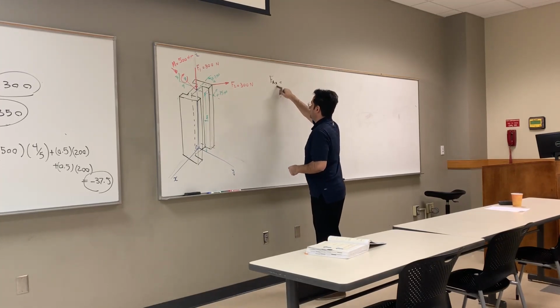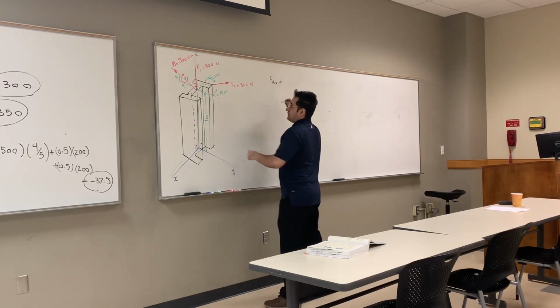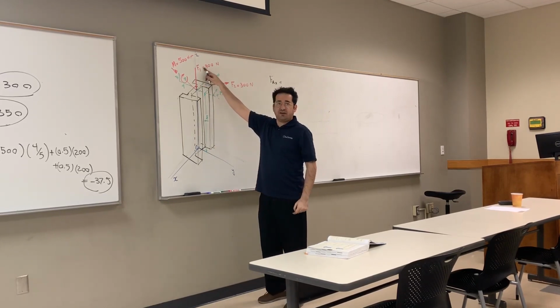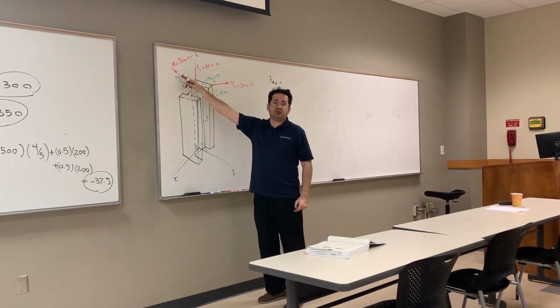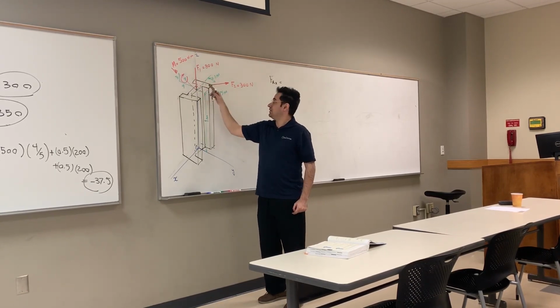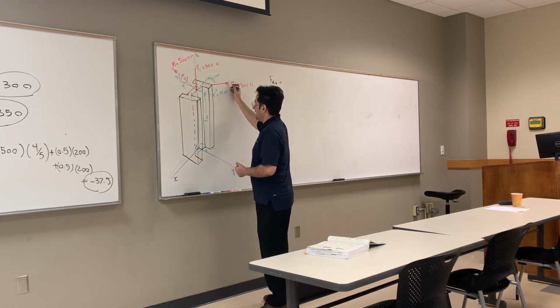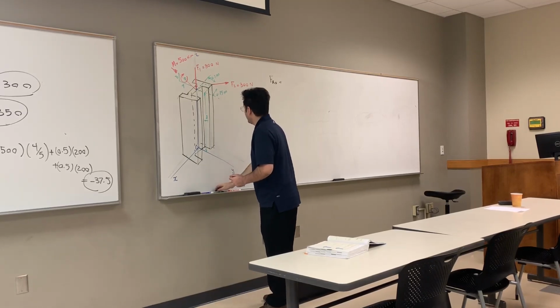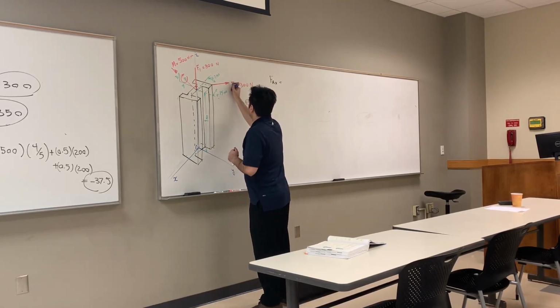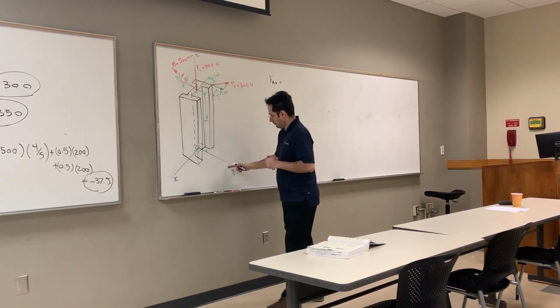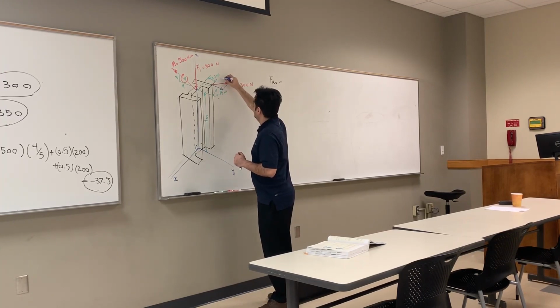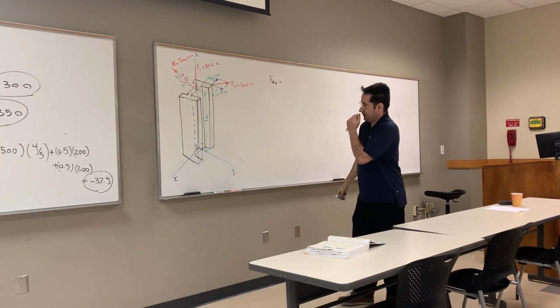So the resultant force x component would be, let's start with this guy. Does this have any contribution to the x component? No. No, z, right? This is just a moment. You don't even add it to the force component, right? So the only thing that remains is this guy, right? So yes, this one has an x and y components. Let's decompose it. This guy, this is the y component. You see, it goes around y. And this one is the x component, which goes in the negative x, right?